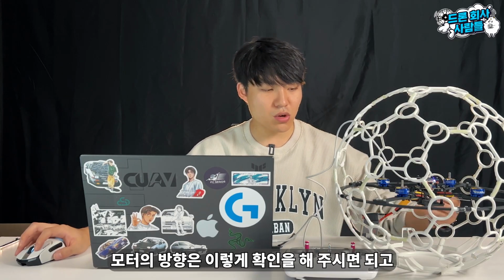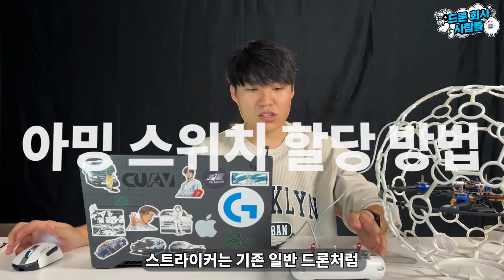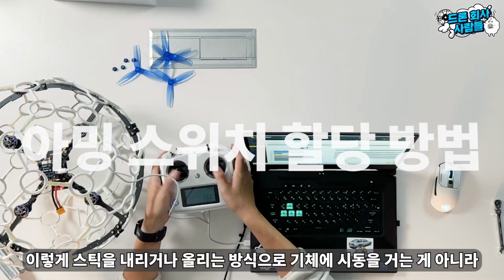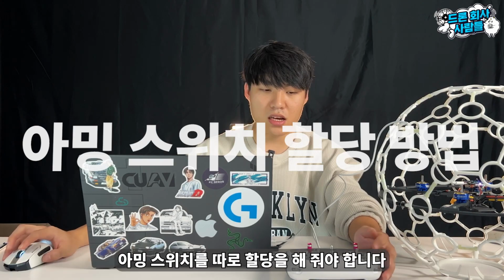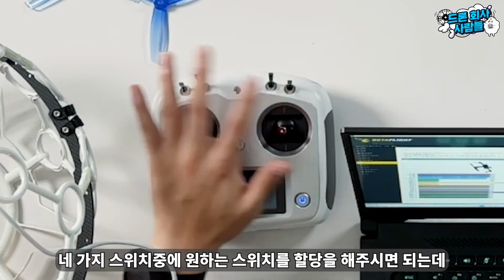You can check the motor direction like this, and for the Striker, just like a regular drone, you use the stick like this. Instead of starting the aircraft by lowering or raising it like this, you need to assign an arming switch separately. So you can assign the switch you want among these 4 switches.